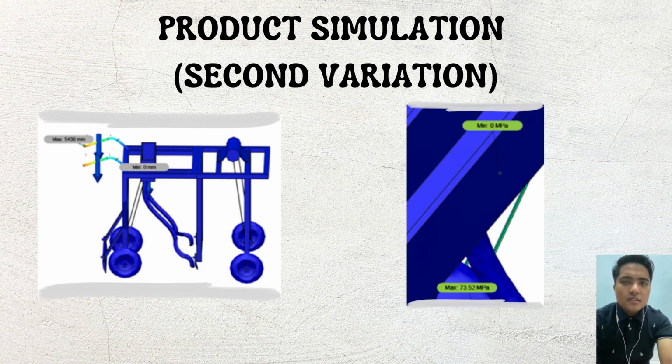The load is still the same as the first design variant for comparison, which is 5 kg. There is a distributed load on the rigid body component. For the second design variant, the maximum value on the rear of the handle was lower than the first design variation. This shows that PVC is less appropriate for the pressure of the user's hand.